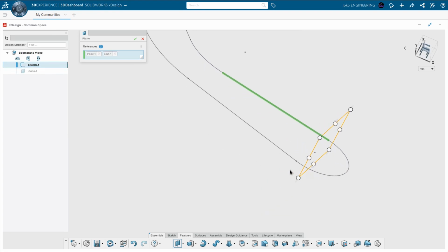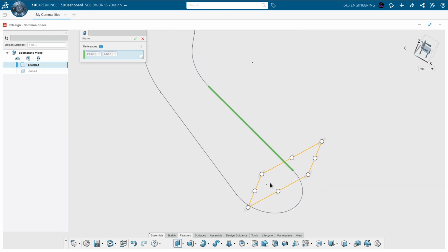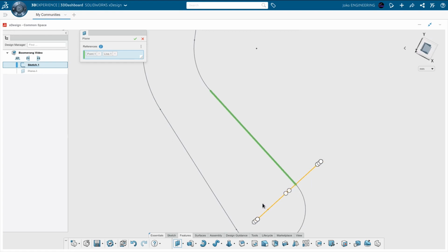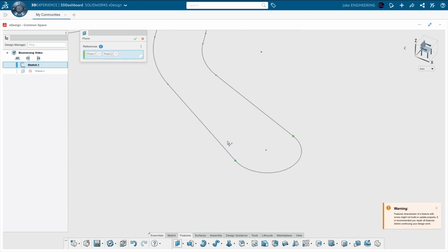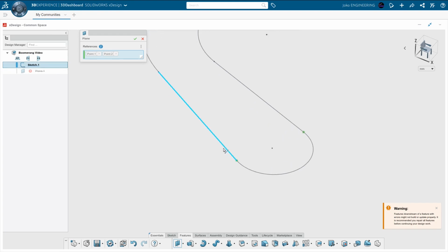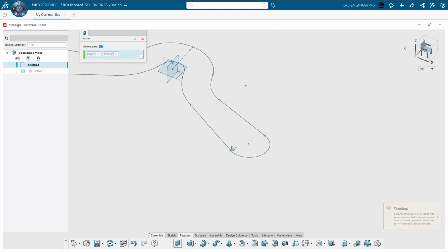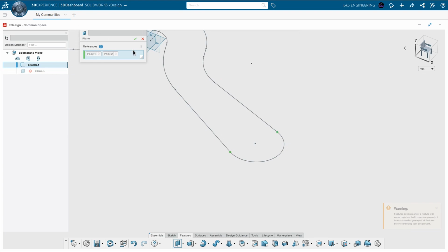So you can choose, just like in SolidWorks, a plane and its point. Now unfortunately, if I want to draw a plane that intersects these 2 points, that's not going to work. So I'm going to get rid of this line. We'll choose this point. And can I choose this line? Nope, get an error. This line, get an error. This arc, get an error. So I don't know if there's a way that I can choose a plane that is quite the way that I want it.